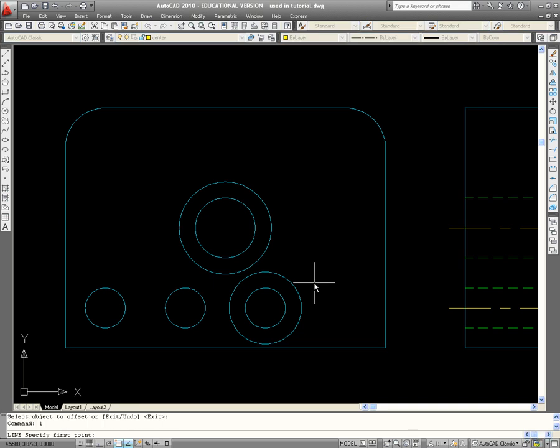Now I'm going to draw lines. Quadrant to quadrant, quadrant to quadrant, enter. I'm going to enter again to do the same thing down below in the smaller circles. Quadrant to quadrant and quadrant to quadrant, enter. When I'm done, I will erase, enter, click the construction circles and the angled lines.